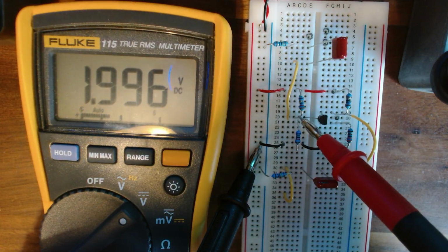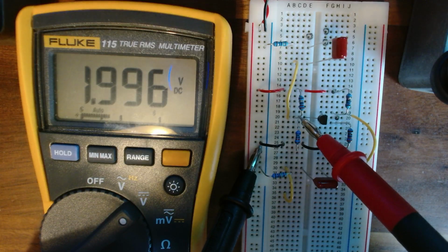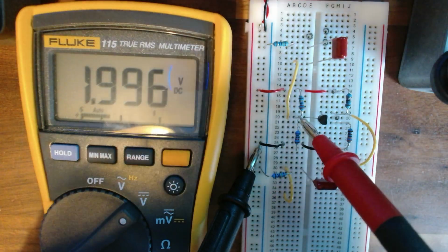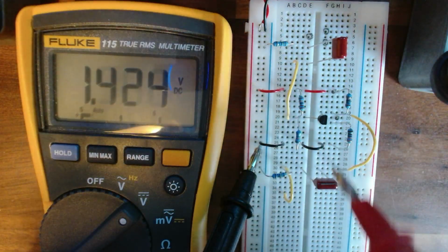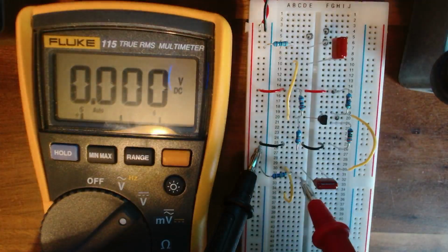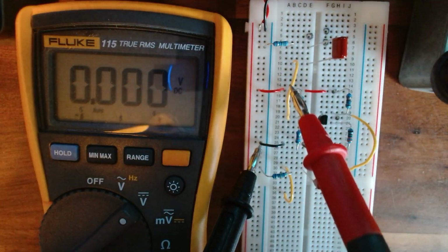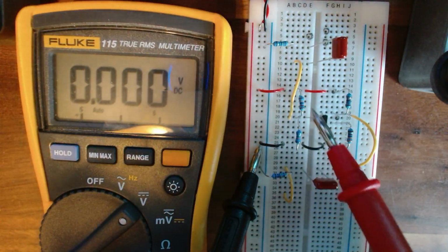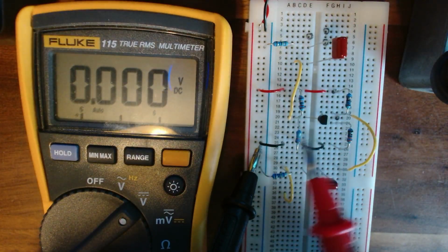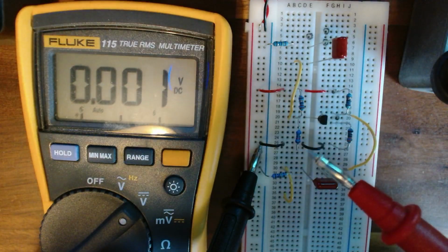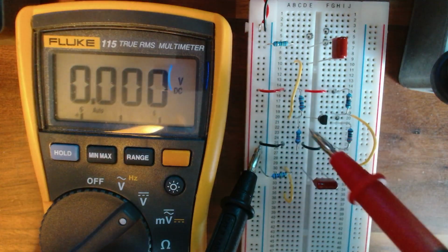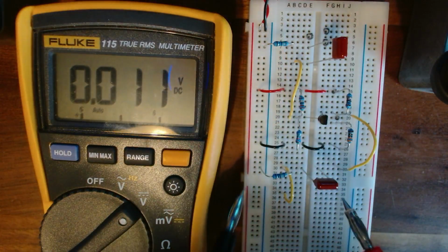If we go in here, it's kind of hard to see, but this point where this yellow line comes in, we can probe here and we can see a number. We're getting 1.996 volts, and we wanted 2.13 volts, but in the real world the breadboard has resistance, which is taking voltage out. This wire has resistance, which is taking voltage out. These resistors aren't mathematically exact, which is skewing results. There are just real world problems that go on with electronics.